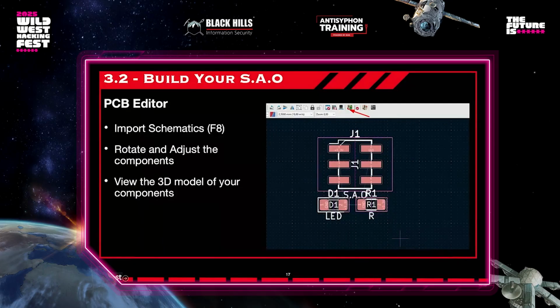Then, once the schematics and the footprints are done, we can open the PCB editor and import the schematics into it. It's going to look like this. On top is the connector, then we have the LED and the resistor. And then you have the option to show the 3D model of each component. It's going to be useful because maybe you messed up the footprints and it's not the right LED that you want to use. And if you have the 3D model, you can see if there is something that's not working together.